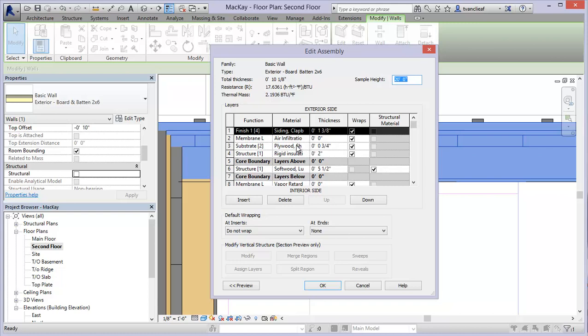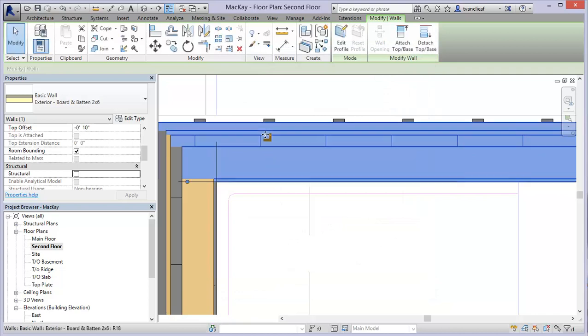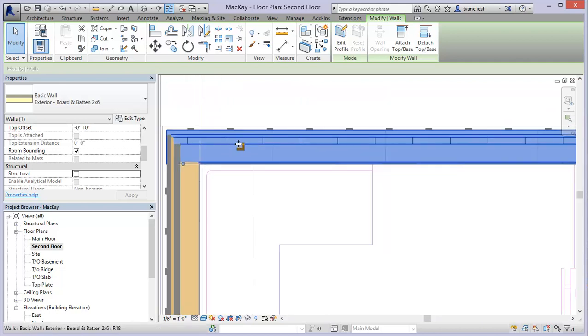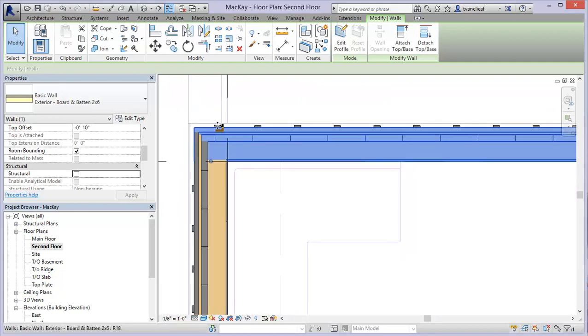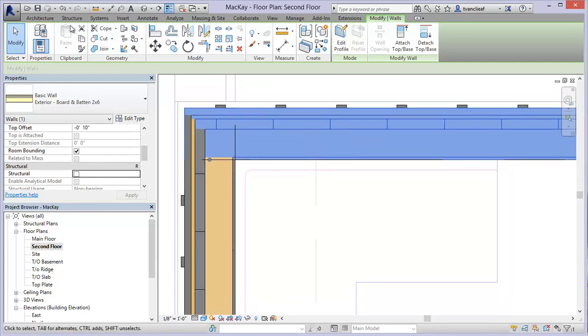But anyway, you can see we have the overall wall type here, and it's going to be the overall thickness minus the thickness of these little sweeps. So with that wall created, I come in afterwards with this profile, and to do that, what we need to do first is create a profile for our sweep. So let's take a look at how we might do that.